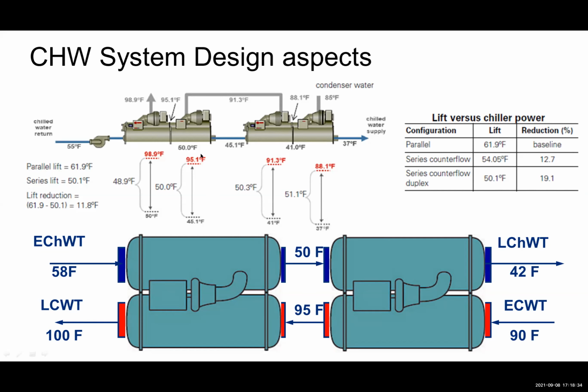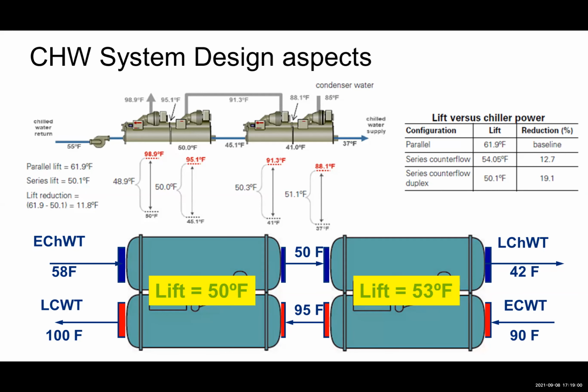So correspondingly, there is a sizable quantity of power consumption on the main equipment, because we talked about 50 to 60% on the HVAC, and out of that, the chiller plant consumes a large chunk. So even if you save 20%, it contributes to almost 5 to 6% of saving on the overall energy performance of the building as well.